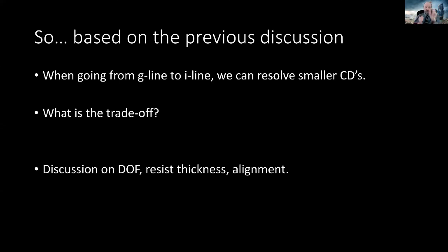There's only certain things that are real critical. In the case of transistors, it would be the gate. The gate size is what determines how big your transistor is, how many transistors you can put per square centimeter, how fast they switch, because if they're smaller, they switch faster. So how many calculations per second can you do, and all of that.